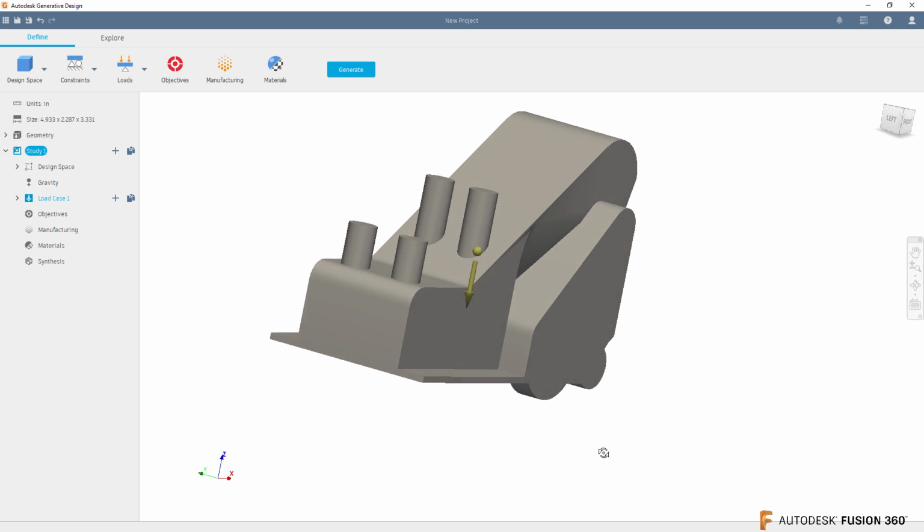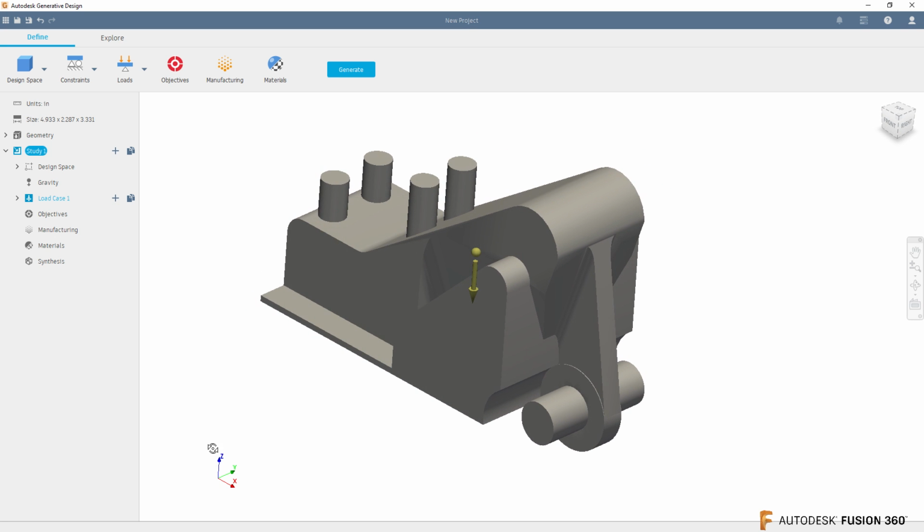Now, I said before, I use topology optimization as a reference. So Fusion generative design is topology optimization with some cool caveat on top of it. Because what topology optimization does is it looks at these parts and then it tries to make the most streamlined version. But generative will actually also take into consideration how it's going to be made, because parts have to be produced. It cannot just be a fancy design.